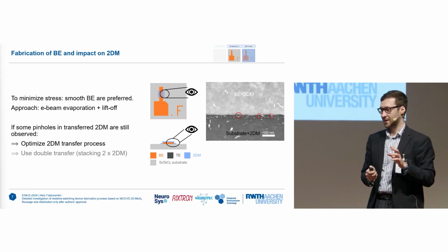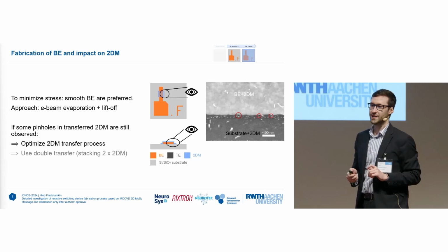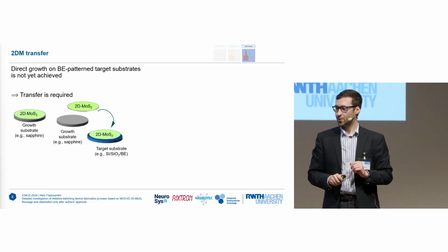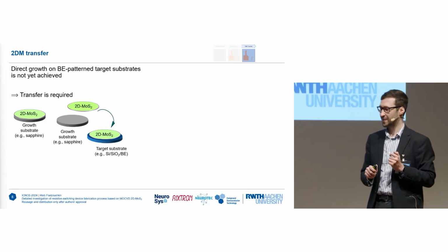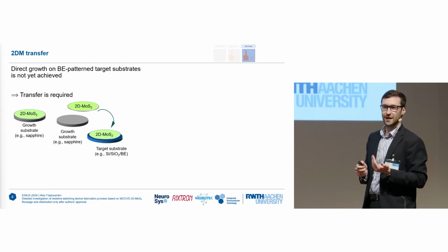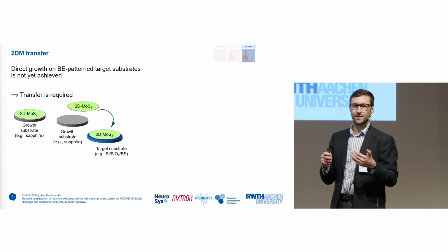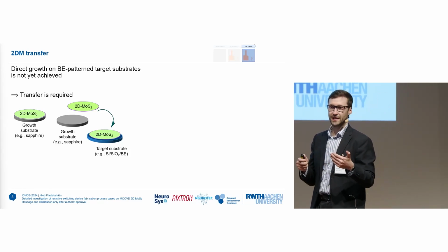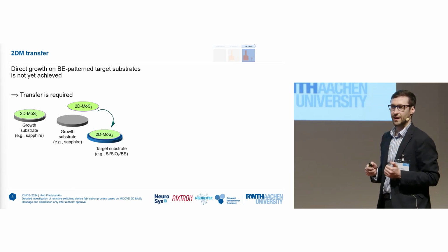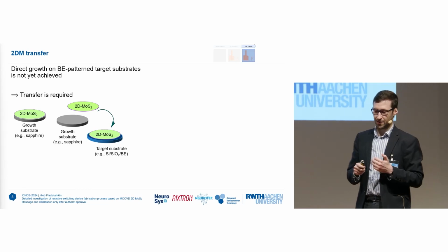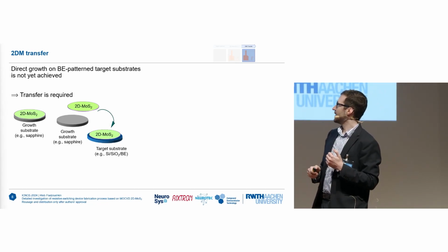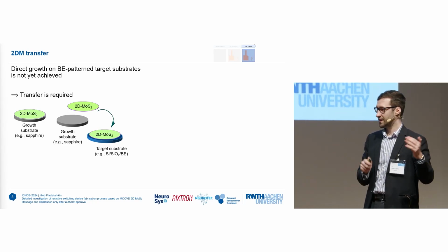Here we'll be focusing on the other one, which is related actually to optimizing the transfer of the materials itself. So, as already mentioned a couple of times, we cannot, unfortunately, at the current point of time, deposit these materials with some scalable technique on the target substrate where we already have the bottom electrodes pre-patterned. So it necessitates this exercise where we mechanically transfer the material from one substrate to another.